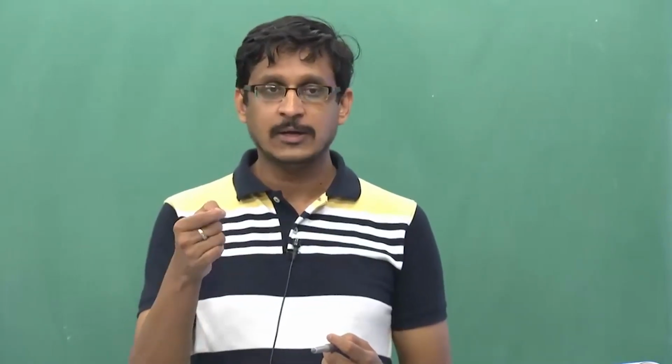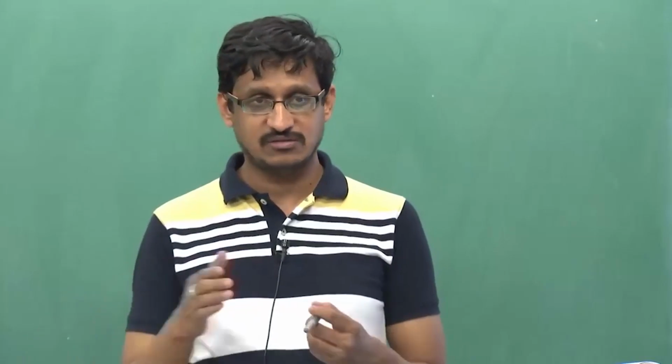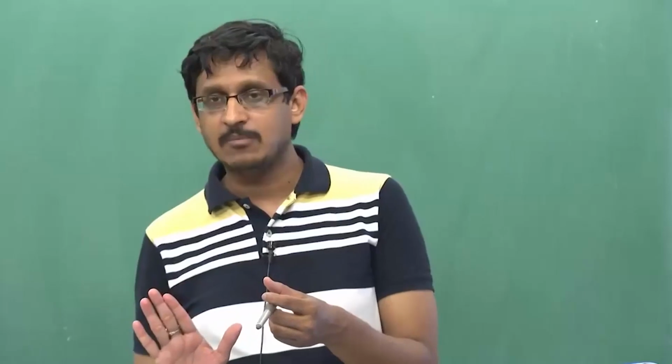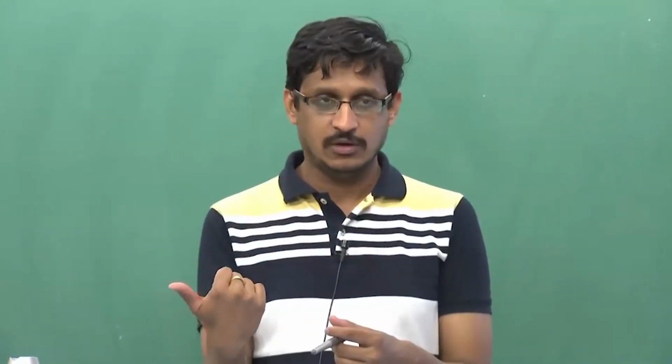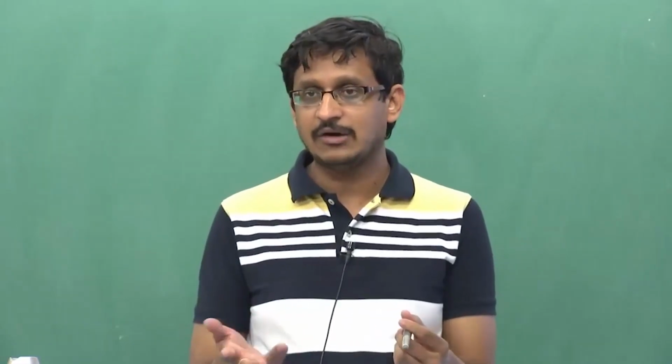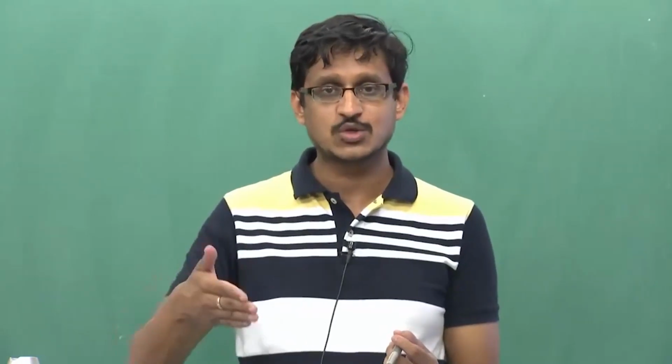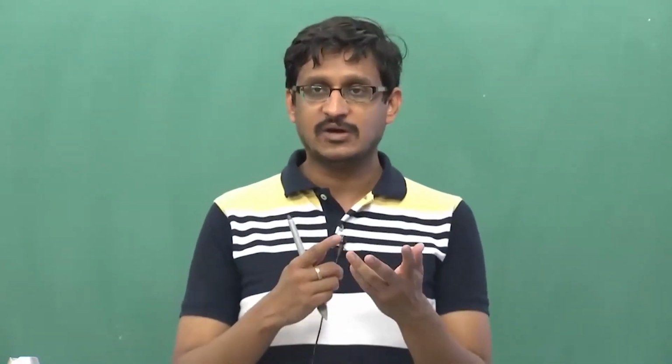0 stands for the way in which it would be behaving in the radial direction, that is, radially how the mode would spread out, and M stands for how it would change azimuthally, angularly. If M is also 0, then it has no dependence on phi, and unluckily or luckily for us there is no such mode as the TE00 mode. So, M has to be equal to 1 at least in order to get the first mode. Okay. So, you get the TE01 mode, similarly you get the TM01 mode.